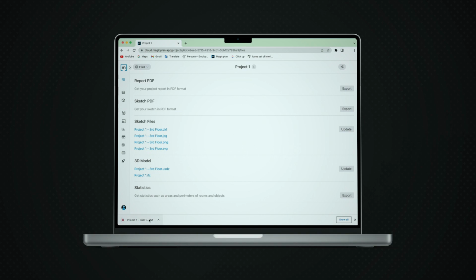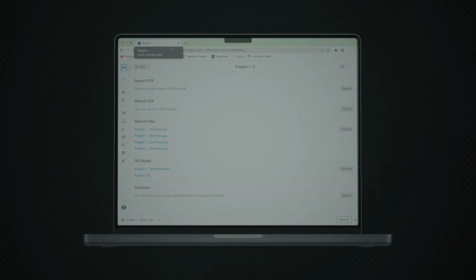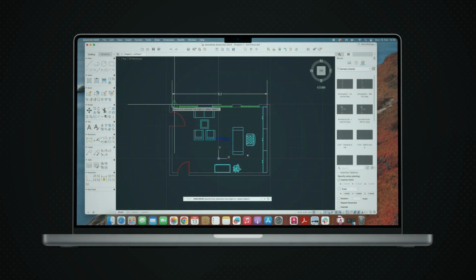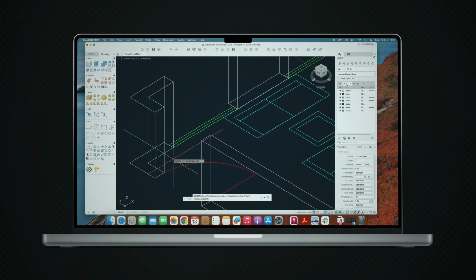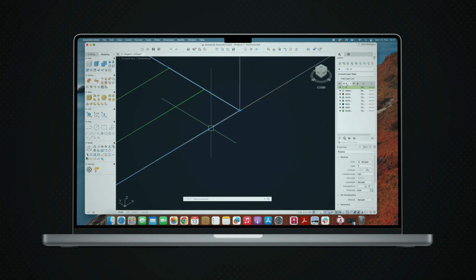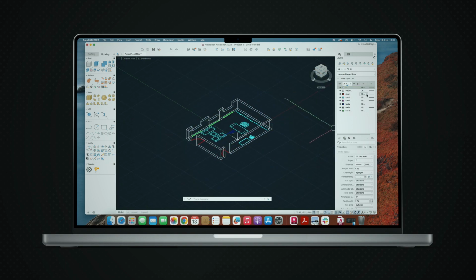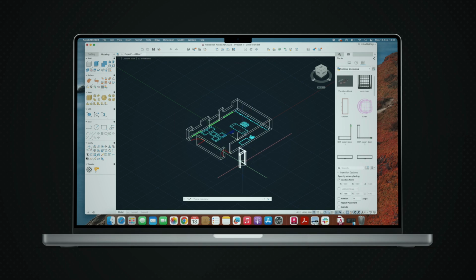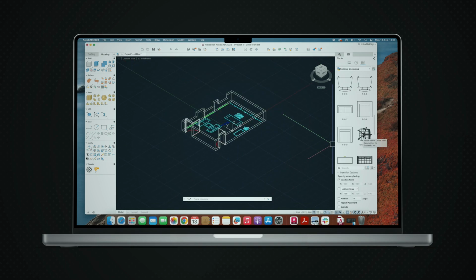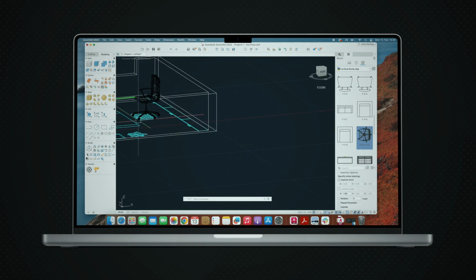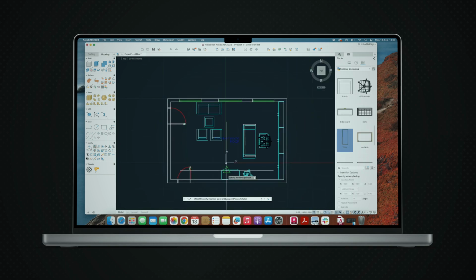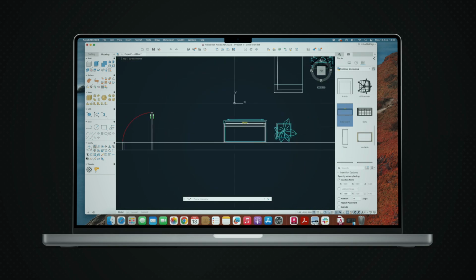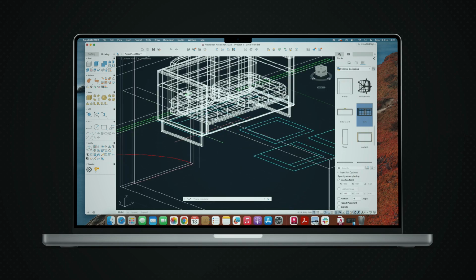Now let's open AutoCAD to import this file and start creating our nice new office. I started by checking the dimensions and modeling each building material in the plan in separate layers. This made it much easier to create the walls. Then I used the furniture blocks that I added to the magicplan floor plan as a reference point for placing the real furniture in their respective positions.